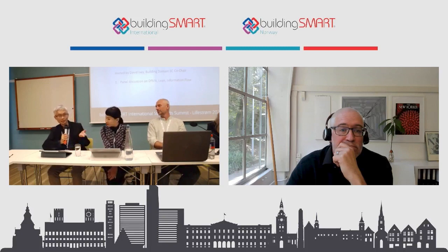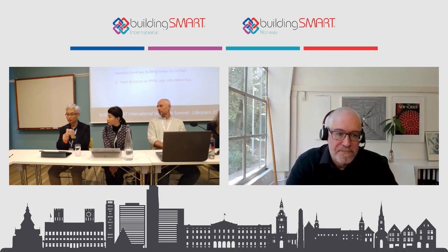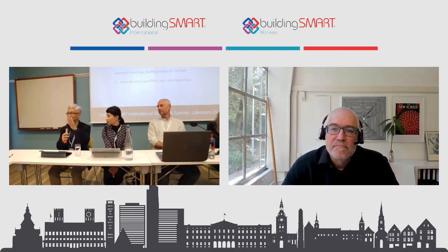Yeah. So just to add to what Vanessa mentioned, it's not just public housing projects. There are a lot of even residential projects now using prefabrication, especially in Singapore. There is a lot of push for PPVCs, or prefabricated, pre-finished volumetric construction, as well as the PBU, which is a prefabricated bathroom unit. So the entire unit, or the PPVC is part of the unit, completely assembled and finished off-site, and then you just bring it and install it and join.